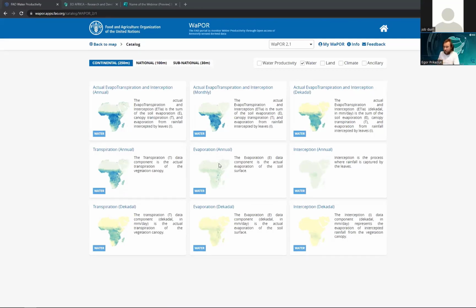From optical remote sensing perspective, how to calculate the ET under cloud cover? No way. If you don't see, you don't see that. But in the Penman-Monteith equation, you don't actually have to see anything. You can estimate the reflectance of your grass. It is called albedo. You can try to measure it on the ground, maybe with a drone, if you want, and then use it in your equation to continue the study.